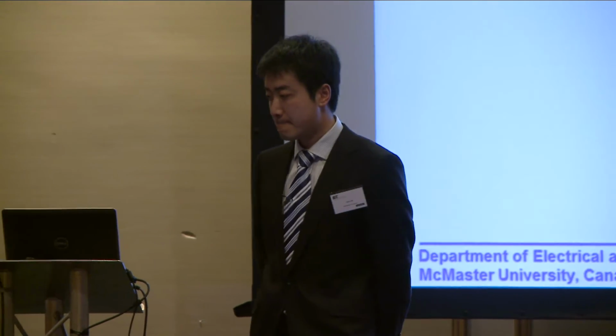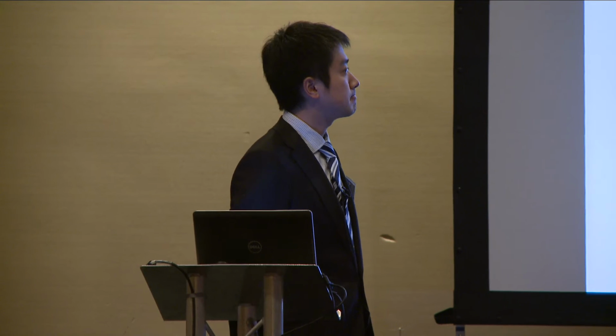And the second, just a general comment, not directly related to your presentation. I think that it's unfair to compare space vector modulation strategies with a sinusoidal PWM without min-max injection. It's a general comment, not only for your presentation.